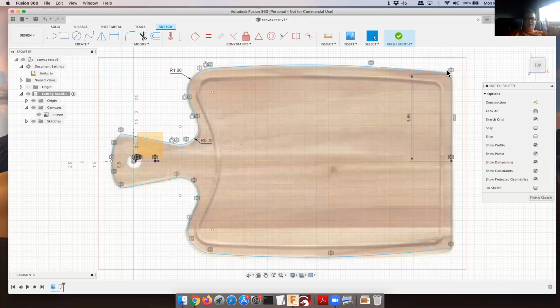Now you'll notice I didn't do the little fillets. I'm going to add them later. I have a question. So you did the coincident arc and line, right? That was the only thing you did? And then you were able to flip the whole thing. Yeah, I wanted to make sure that the endpoints of the arc and line were on the line of symmetry, and that the center of this arc, because the arc bridges the symmetry, was constrained also to the line of symmetry. Okay. Now, you notice my lines are blue, they're not fully constrained.